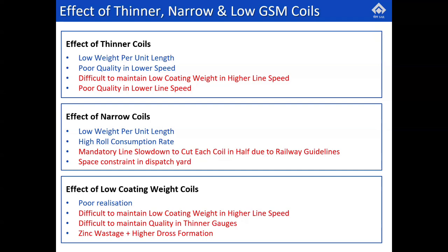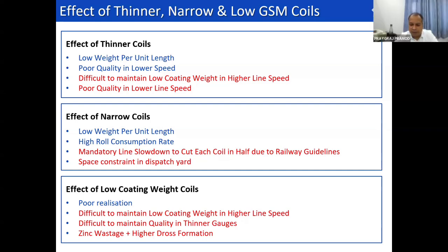I'm not saying that it cannot happen. Like you have rightfully mentioned, if it is coils from the same shift, maybe we need to increase the drossing frequency. I would request you, sir, to please share the coil numbers. I will be backtracing it and coming back to you with the detailed CAPA. Also kindly share the photos. If you are getting such things, try to share the photographs. Sure, sir. Sure. I do have that.